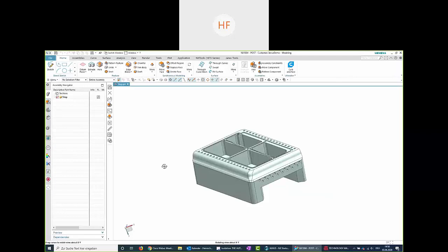By clicking on OK, and the second time when I click on OK, I have to ask you to figure out how the blank material once looked. It had the dimension of the first reference part. But when I click on OK, we see that the blank part has updated itself automatically. I did not change it. It updated automatically, not just the blank part, but also my clamp situation. When I switch back to my CAM setup, I see that the blank part got bigger. Therefore, those mobile vices of my fixture also moved accordingly.